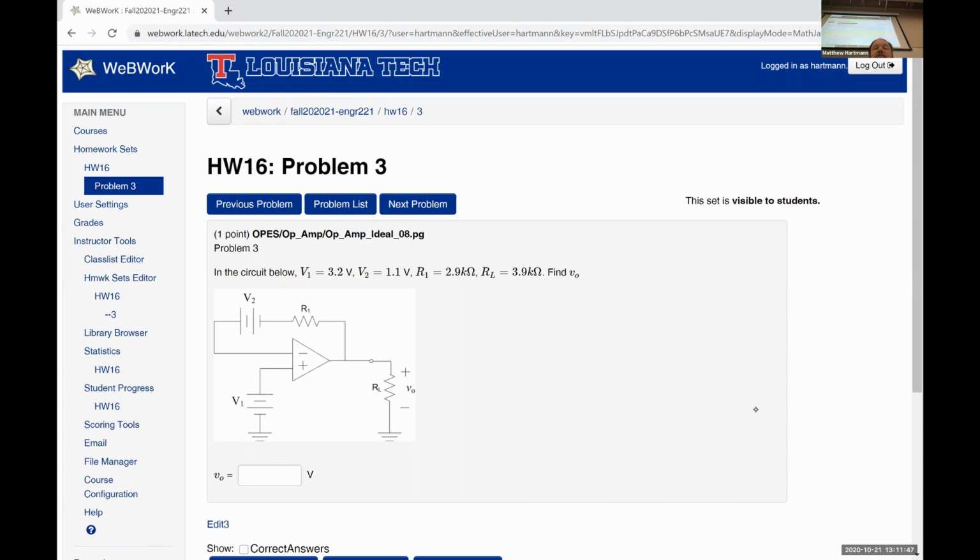Consider that the current through the resistor R1 is flowing to the left. Where's it going to wind up going? It's 0, because it would flow into the input terminal and that can't happen. So that resistor R1 there is to distract you. So you would have negative V1 plus V2 plus V out is equal to 0, which means V out is V1 minus V2, I think here.